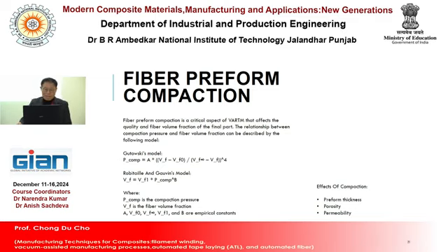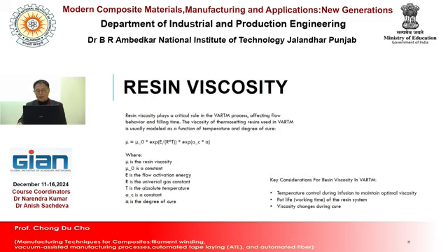For resin viscosity, we use this kind of model, which considers temperature control, the part life of a resin system, and viscosity change during cure.